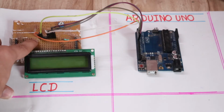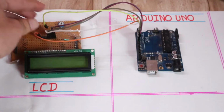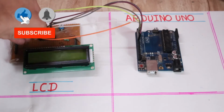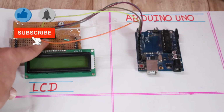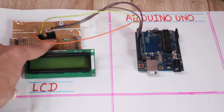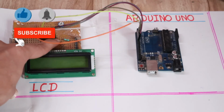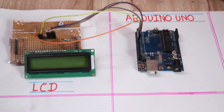I will again repeat: the RS pin should be connected to pin 2 of Arduino. The enable pin of the LCD should be connected to pin 3 of Arduino. Then the D4 pin should be connected to pin 4, the D5 pin to pin 5, the D6 pin to pin 6, and the D7 pin to pin 7 of Arduino. So this is the connection of the LCD.